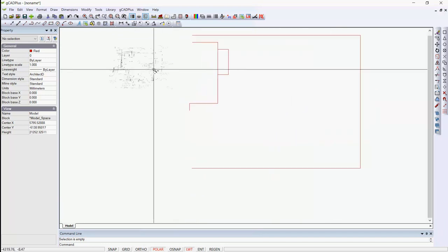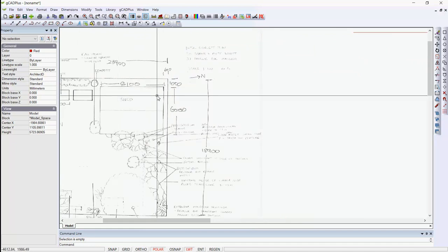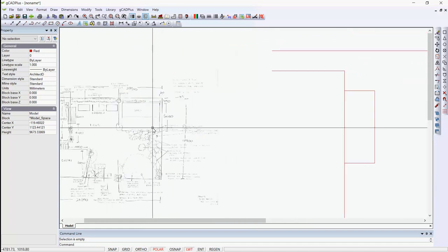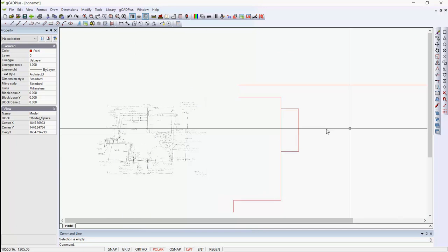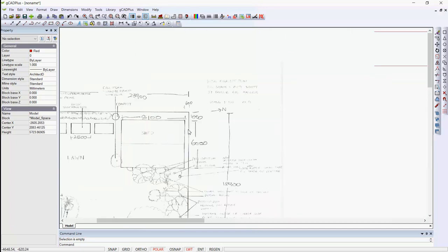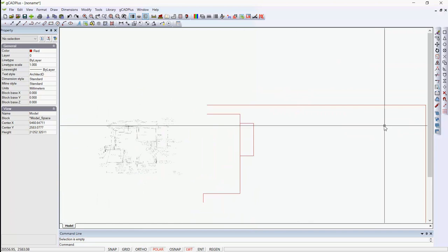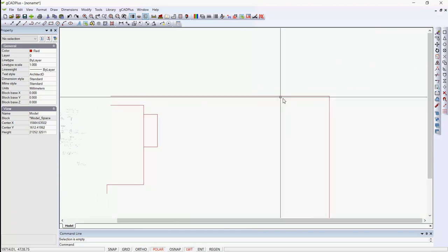We have a shed. Let me just refresh your memory. We have a shed that's 8100 by 6000, and so it's an easy job to put that in. The shed is 600 millimeters off from the back boundary and 1000 millimeters off from the top boundary. So again, we can use our offset to locate the corner.